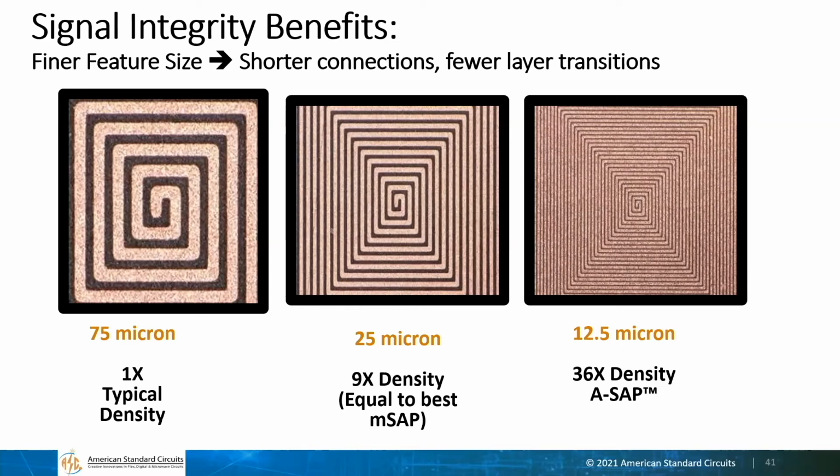That's 9 times area density. And then they tried out their 10 micron head, which they'd never been able to try out before, and it worked fine. They got down to 12.5 microns, which was the smallest feature size they had on that design. And that's 36 times density improvement for them without them spending a bunch of money on expensive new lithography tools or other capital equipment. They had already spent that money on the capital equipment earlier, just weren't able to leverage it.